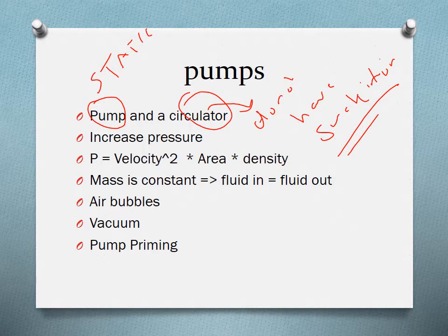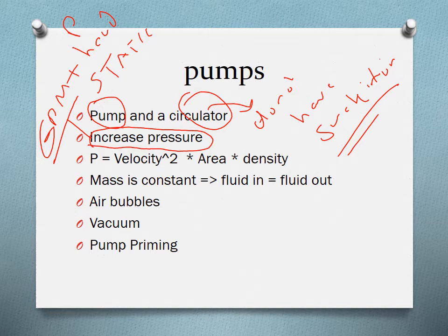Okay, and so pumps can increase the pressure. This is the purpose of both circulators and pumps, to add some pressure to the water. There's a lot of engineering that goes into making a pump, and there's too much involved in pump selection. But there are two things you have to know about pump selection. One of them is the GPM, and the other one is head. By head we mean pressure, and GPM is gallons per minute.